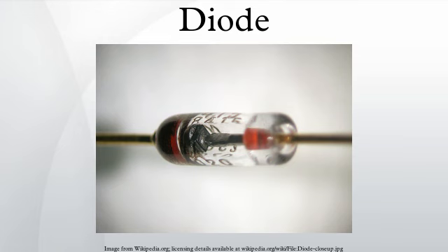The diode's terminals are attached to the N-type and P-type regions. The boundary between these two regions, called a PN junction, is where the action of the diode takes place. The crystal allows electrons to flow from the N-type side to the P-type side, but not in the opposite direction. Schottky diode. Another type of junction diode, the Schottky diode, is formed from a metal-semiconductor junction rather than a PN junction, which reduces capacitance and increases switching speed.